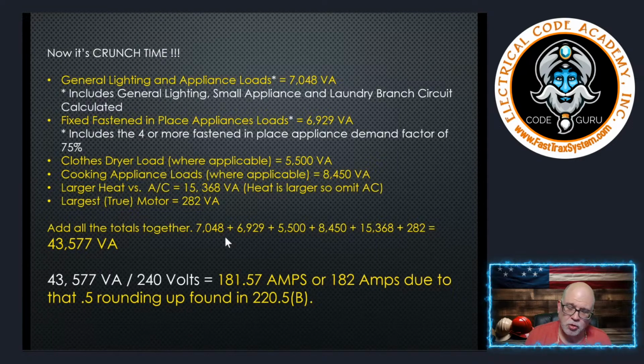In the code, if it's a 100 through 400 amp service, a 3-wire 120/240 volt for a single family dwelling, as in our case, you're allowed to apply some rules that are in 310.12. And we refer to these rules as the 83% rule. Now, this usually yields one size smaller than what you get in 310.16.